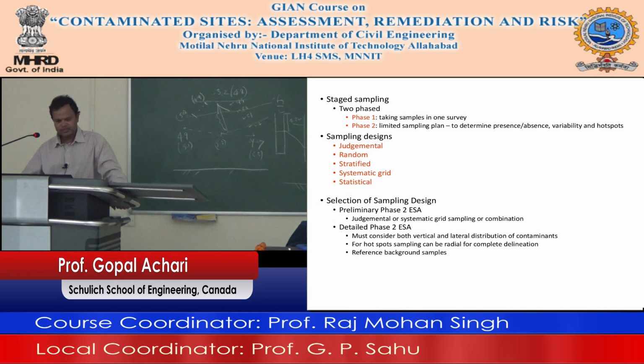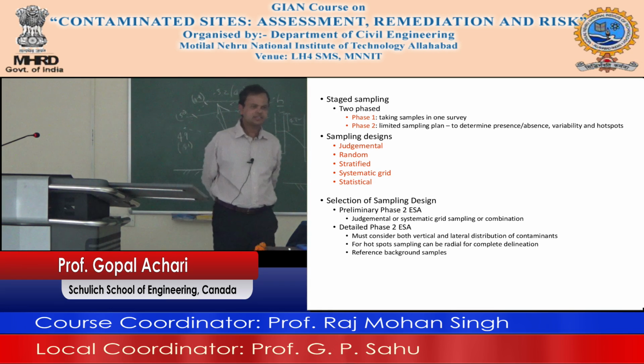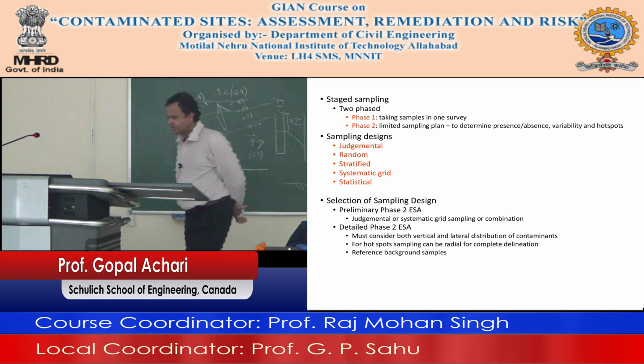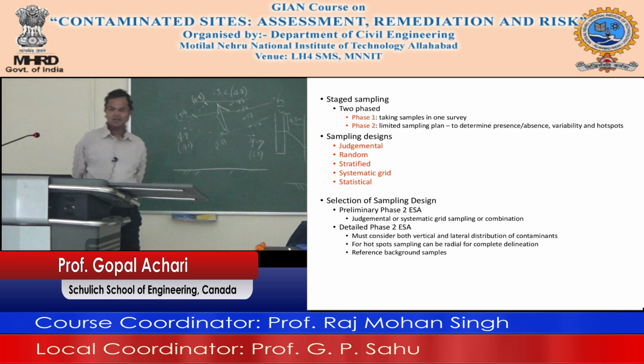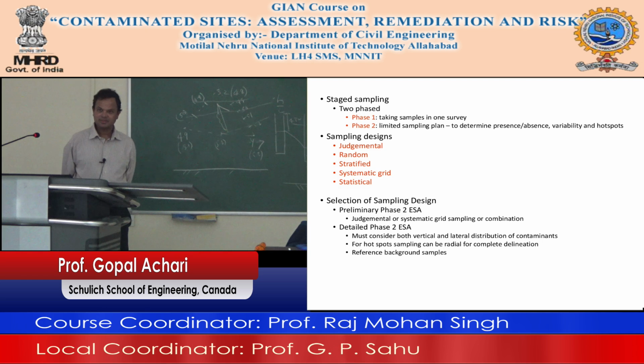Stage sampling: there is two-phase sampling. Phase 1, taking samples in one survey. Phase 2, limited sampling plan to determine presence, absence, variability at hotspots. So when you budget this, you have to always keep some money aside for supplemental analysis. At least 10-15% of the budget, you should keep aside, thinking you will have to go back and resample. Because when you send samples to the lab, you will be surprised how often you get surprised with the results that come back from the lab.